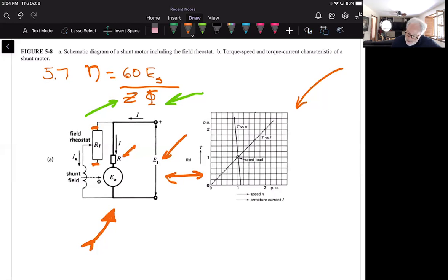Excuse me, I've got that just the opposite. This would be minimum resistance here, and this would be maximum resistance here. And by changing that resistance, we can change the I sub X, or the excitation current. And then, according to the equations that we've all worked through, changing that excitation current, increasing the flux, changes the output voltage, right? So we got all that going on.